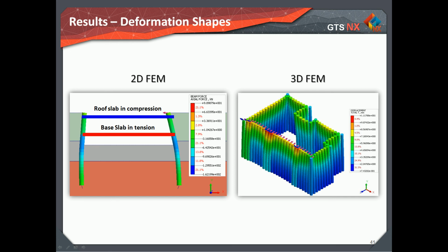The limit equilibrium model did not consider the initial mobilized passive resistance at all and suggests a huge base slab load, but with the roof slab in, it suggests a more realistic number, but still based on an incorrect approach, therefore a problematic function of the method.